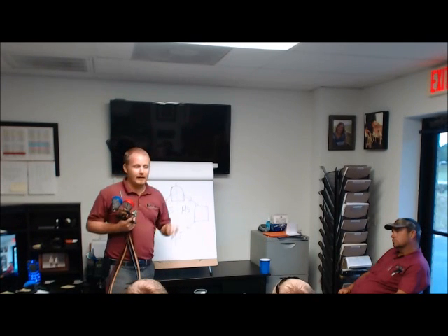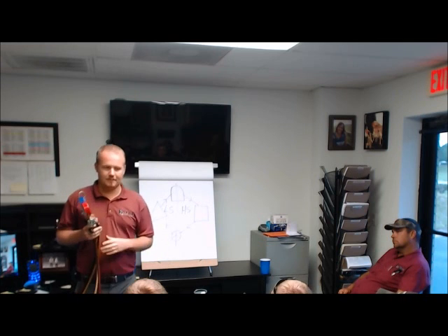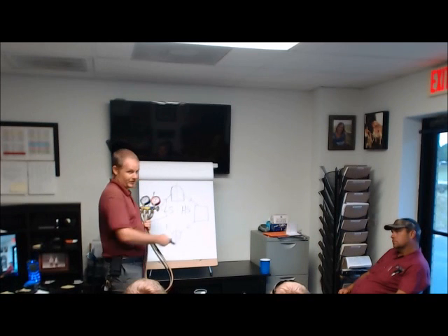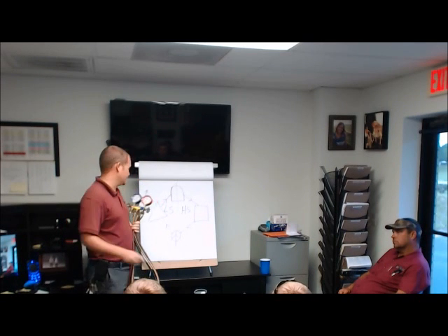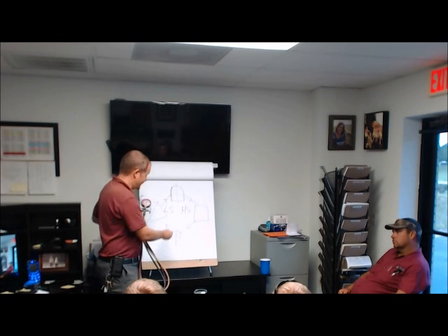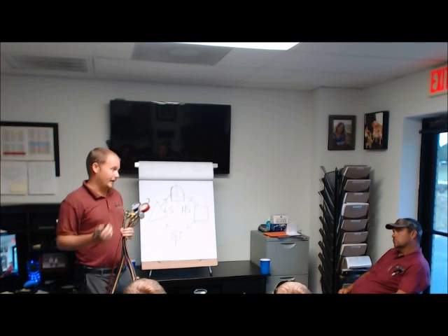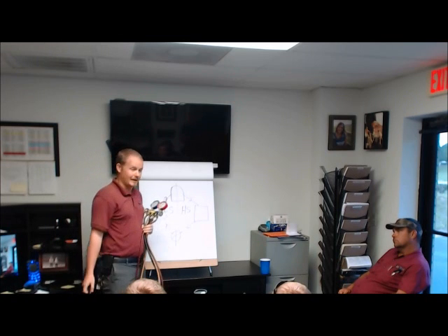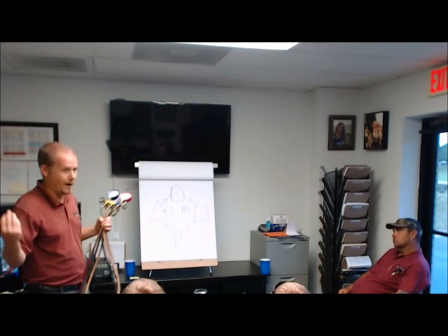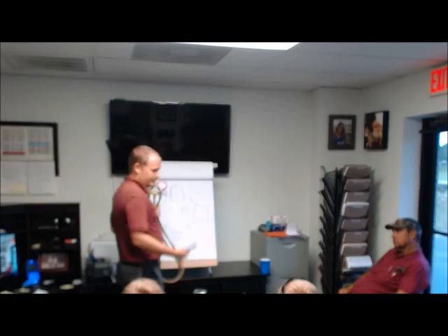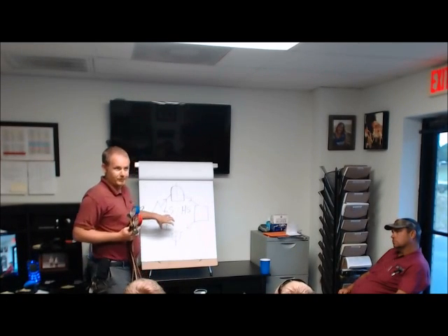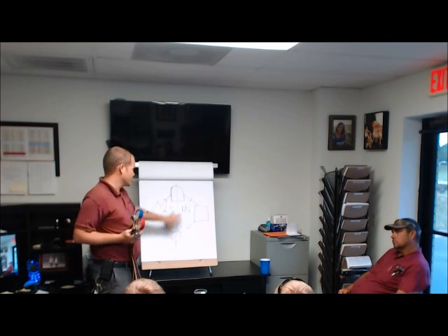Why do we insulate the liquid line on a ductless system? Because it's not a liquid line. It's actually an expansion line. Because the metering device is in the condenser in a ductless system, all these are in one place, and now you have a line that travels through there. So this is a cold line. Your small line is a cold line. It's actually not a liquid line at all. It's actually an expansion line. It's a low pressure flash gas line, which is why it'll sweat. Now, they're not necessarily all that way, but that's how a lot of them are. So anyway, it is a real thing. I'm just using that to demonstrate expansion line is actually a real thing. It all just depends on how these are positioned.